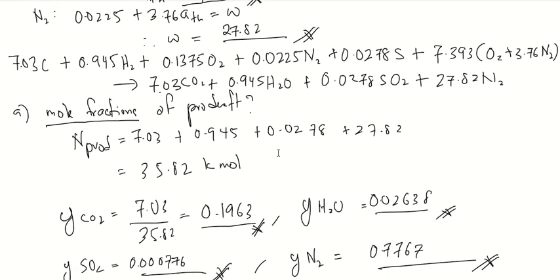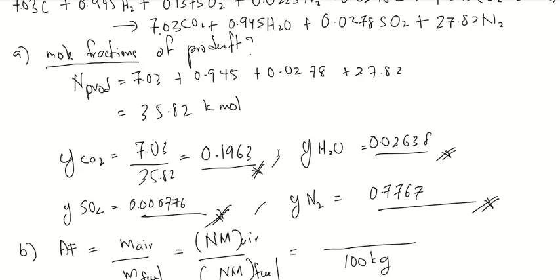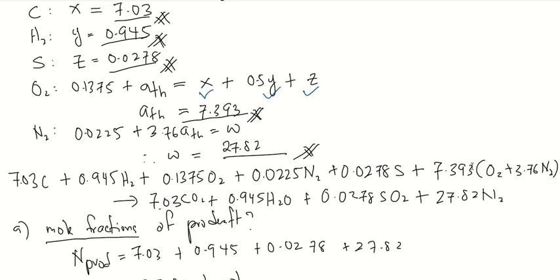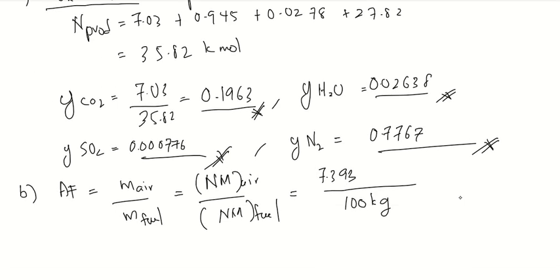Here it is almost similar to the previous example. So 7.393, which is this value, you multiply with 4.76 kilomole because of air, then multiply with the molar mass 29. So here you have 10.2 kg of dry air per kg fuel.